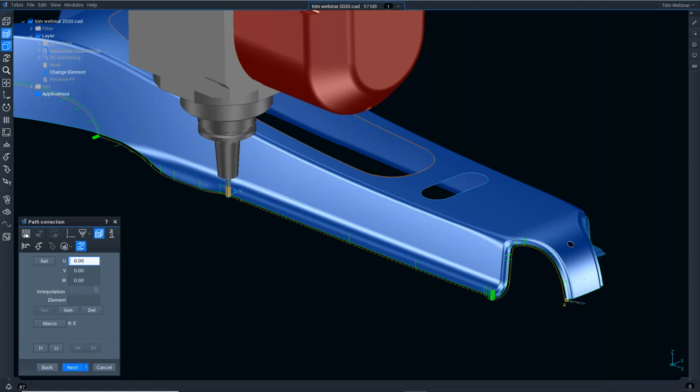So where the tool is at a certain depth, if you consistently cut around and around in that area, you'll get localized wearing. So not only is that inefficient for the cost of tooling, because you're wearing the tooling out very quickly, it also means that there's a lot more work needed to control the sizes of the component. So by moving the tool up and down the flute, what we're able to do is spread this wear up and down the entire flute, therefore prolonging the tool life and making more consistent parts, better quality parts.